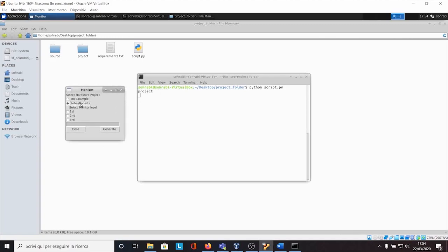Select the level of the monitoring system to introduce in the hardware design. The second level monitors the latency, while the third level performs a runtime verification. The first level measures the number of bytes effectively processed by the accelerator, but we are not interested in it for now. Press Generate to obtain the monitored project. A new folder, named project_monitored, will be created, and Vivado will be automatically opened at the end of the process.